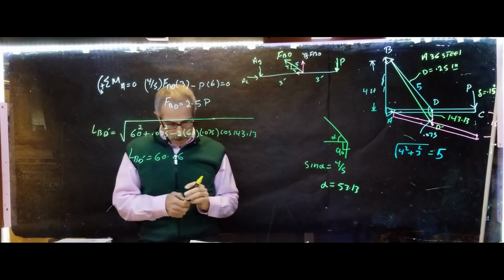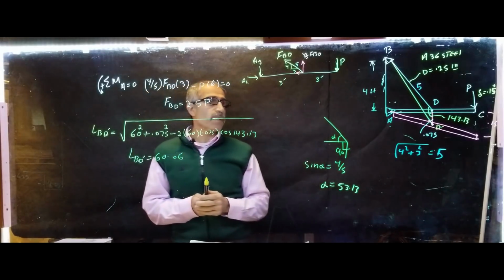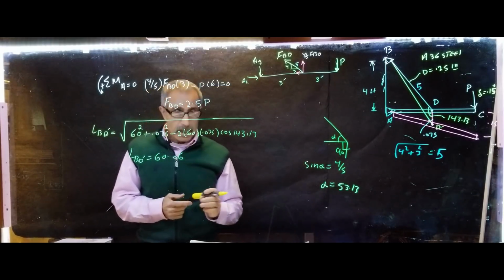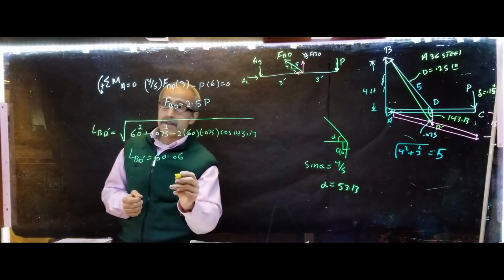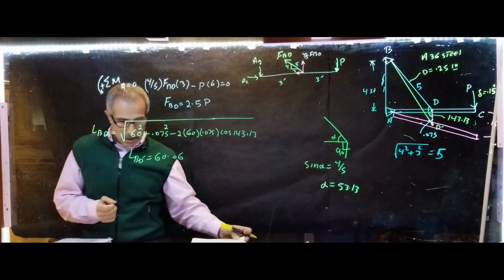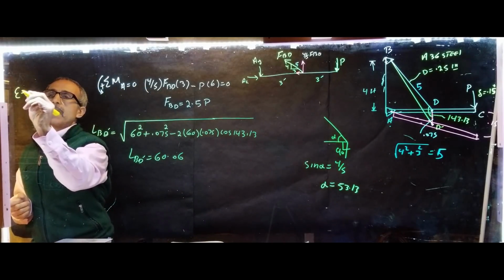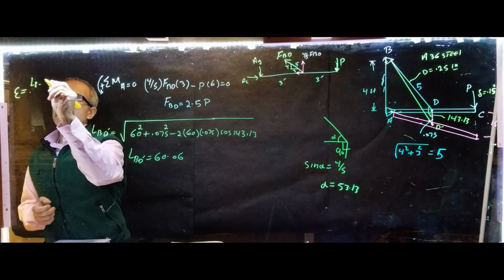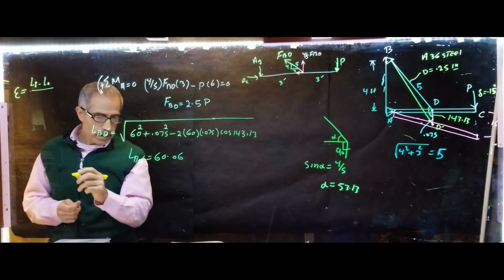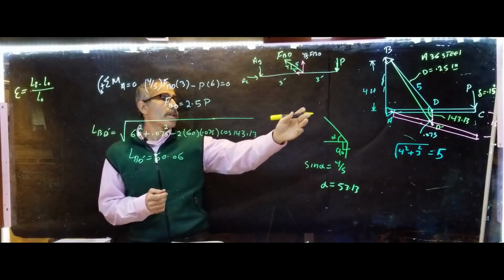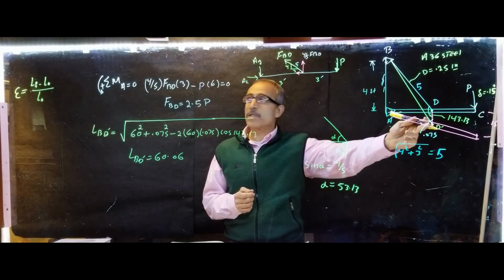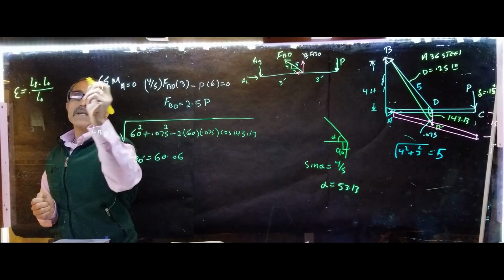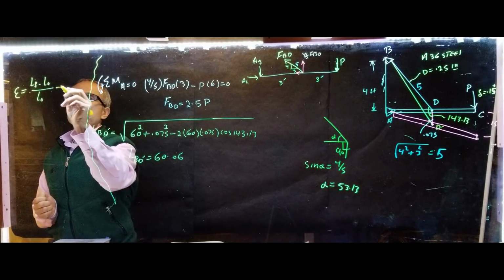Okay, so now I have that. Then what? Of course, we have a bunch of formulas we can use, and we can figure that out. You remember that strain was, let me write it here. Okay, it was the final length minus initial length divided by initial length. So our initial length over here is 60 inches. Our final length is 60.06. So divide that out.